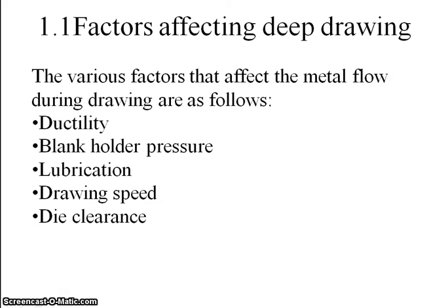Too high values of the blank holder pressure cause higher frictional forces and may cause the metal to be restricted and result in tearing of the cup wall. Lubrication. In drawing, a lubricant is generally applied to reduce the friction.